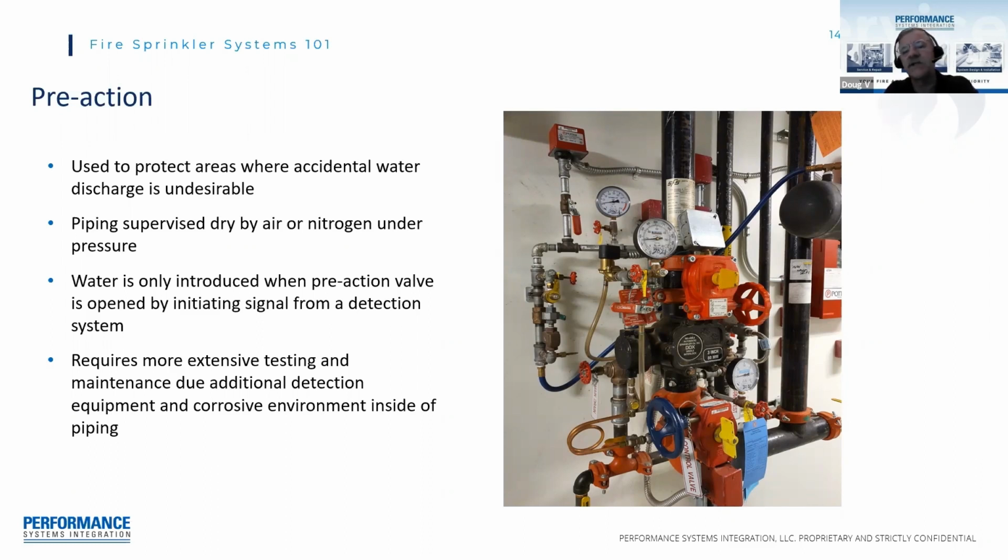So in a pre-action system, you could literally knock a sprinkler head right off the system and it would discharge the air and set a pre-alarm, but no water would be discharged until another action happens, like a smoke detector going off or a heat detector.